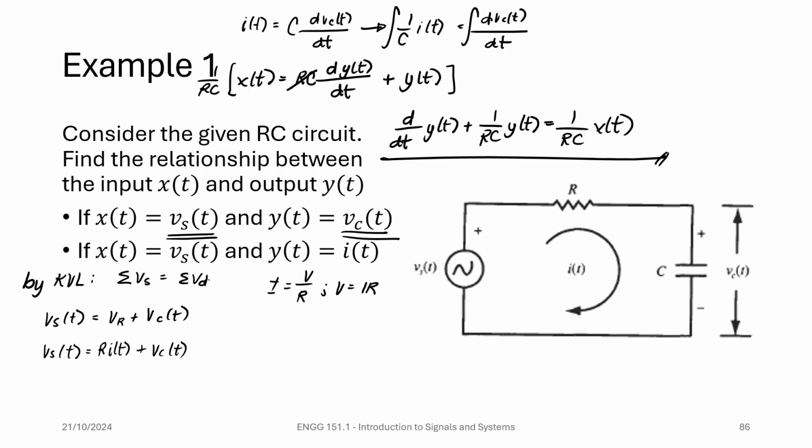Why is that so? Even though we're not turning it on, let's say if there is a switch here, technically the circuit is working in the sense that there is already current waiting. We just don't know when it started, because we don't know when it was plugged in, right? In this case there is no switch, meaning the voltage is constantly supplying the two components. So we're going to have the limits from negative infinity to t.